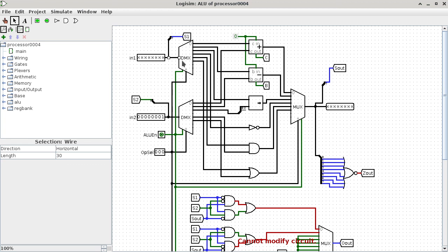So now the question is, somebody has to tell me which output connects to this input here. That question is answered by the gray dot. See this little gray dot here? That is your selection. It will give you a number corresponding to the output index, or the index of the output pin. See this 0 here? That's telling you this wire corresponds to output 0. This is output 1, output 2, and all the way to output 7.